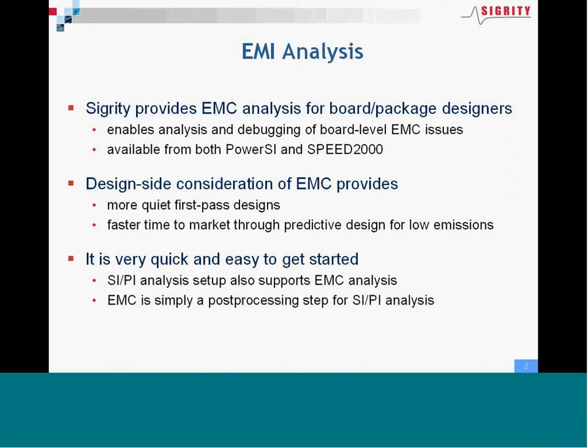Sigrity has a couple of products in time domain and frequency domain analysis for boards and packages that address emissions. What we do is we target board and package designers, not so much EMC compliance engineers. The design objective and the analysis that we produce is really for board-level EMC issues for board designers. It's design-side consideration of emissions, and that means what we're focusing on is the board design process itself and the issues that board designers can influence with their layouts and signaling.